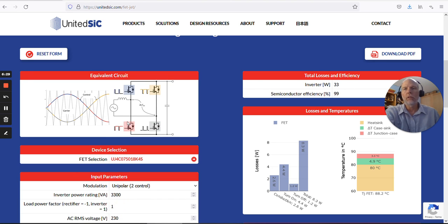If we look closely, the load frequency has been doubled. So in other words, the frequency seen across the output of each leg is twice that of the other modulation methods. So this is a real advantage, because without any additional switching loss, you can double your switching frequency at the load.